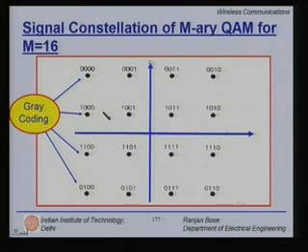So not necessarily that it has to be a power of 4, but a power of 2, yes, because we would like to have them in pairs, specifically when mapping the bits. So if it's 5 bits per symbol, then you will have 32 symbols, right? I cannot have 17 QAM. I cannot map my bits.